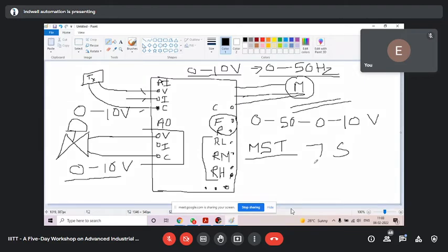The same: as you stop the motor, it will take time to go to zero speed. Zero speed means its shaft will be stopped, braked actually. That time we can set, if we want 10 seconds. As you press stop, it will take 10 seconds, and in exactly 10 seconds, it will stop your shaft. I have given 1 second. Yesterday you saw the direction was changed, in the video you can see. In 1 second, it will change its direction, in 1 second it will stop.